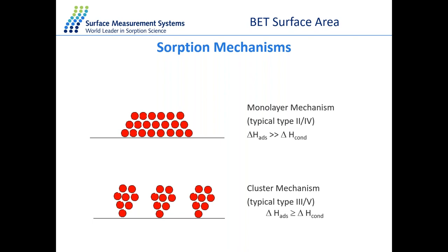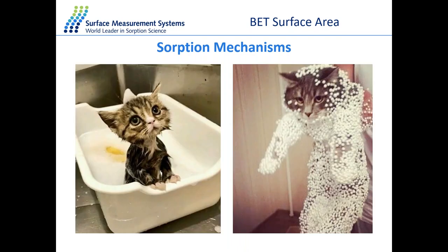However, if that material is being treated or coated with a specific polymer, the polymer surface usually has a lower level of hydrophilicity. Consequentially, it will form droplets rather than spreading uniformly. So it won't allow you to use water on the surface of the sample, but it will require a different solvent. Technically, it's based on surface contact. It's based on surface interaction and energy of equilibrium. You can see basically this example. You want a uniform coating, not droplet formation.